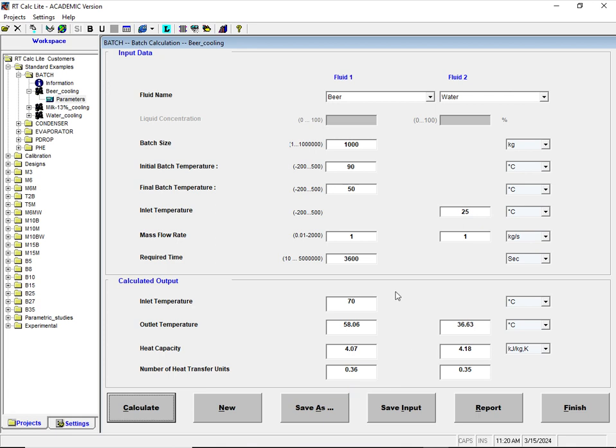So this here is your design parameters. These are design parameters you put into your process specification sheet. So when you actually spec the heat exchanger, or you go to the manufacturer and say, okay, I want a heat exchanger there, and you as a process engineer know this and that is available to you, this is the exchanger that you must design to. And a lot of process engineers actually don't know, a lot of heat exchanger designers don't even know all this. This is now a process engineer's forte. And you then go ahead and you spec that out.